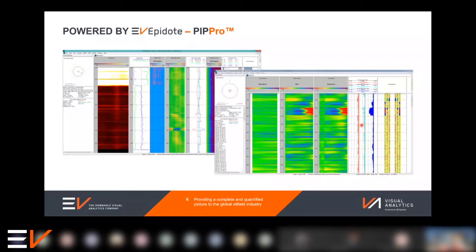And building on that, we also have the PIP platform, or the pipe integrity platform. This takes what we did with MIPS and adds in a lot of extra functionality to give a comprehensive cased hole analysis suite. So this would include the addition of spectral acoustic tools, cement evaluation, magnetic flux leakage, multi-barrier pulsed eddy current technologies, and a whole host of file handling and display updates to handle that additional data set.